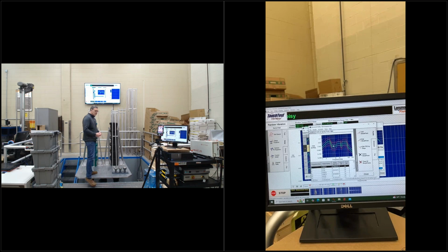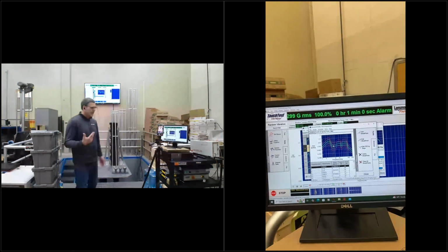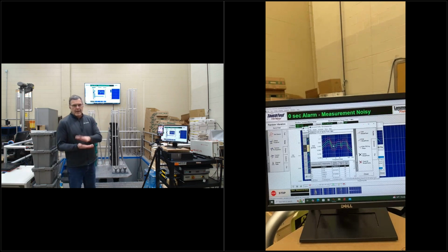Usually the frequency when things start to bounce with a certain input displacement is about 4 to 4.5 hertz. And then once that happens, and you can actually stick a shim underneath whatever's being tested to prove that it's bouncing or leaving the table, you set it there and you let it run for about an hour, over 10,000 impacts, boom, boom, boom. That's not vibration, that's impacts. And it's a severe test. And if you pass it, more power to you.